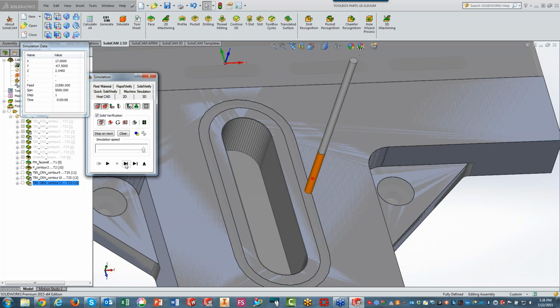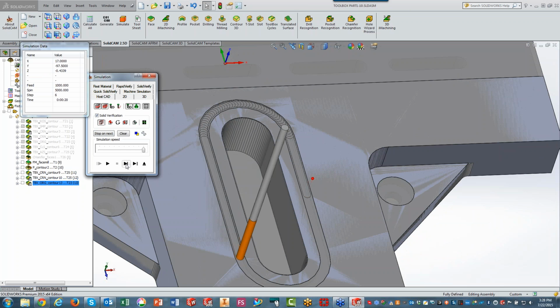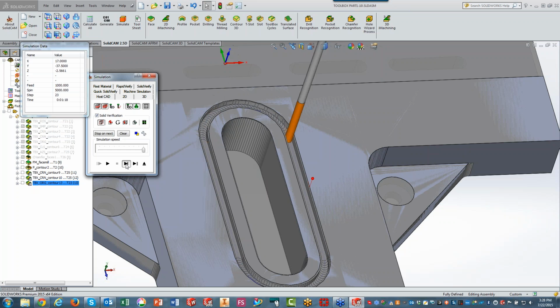You can see that my tool is actually going in with a helical descent into the part itself, exactly in the middle. Now, once it gets to the bottom, it'll automatically clear those walls and then go over to the next side. Okay? Note, all this was done in one simple operation.